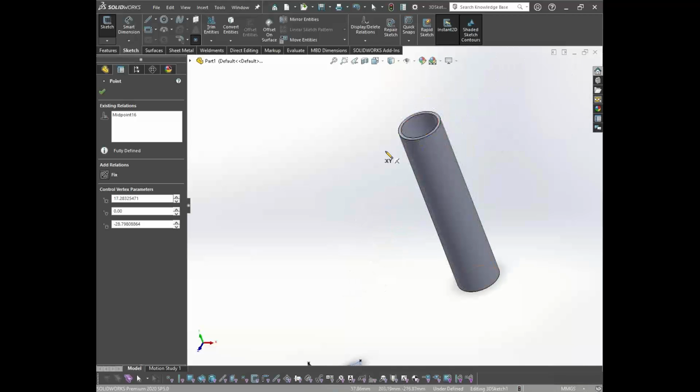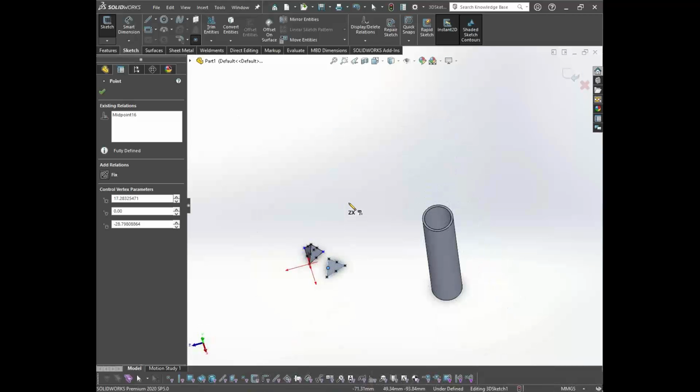So one thing you can... yeah, but when you move to the industry, if you are working as a design engineer, by his point of view, if you are designing a certain component which has a yield strength of, let's say, 250 MPa, and your design requirement is that your stresses may not go beyond this particular yield strength value.